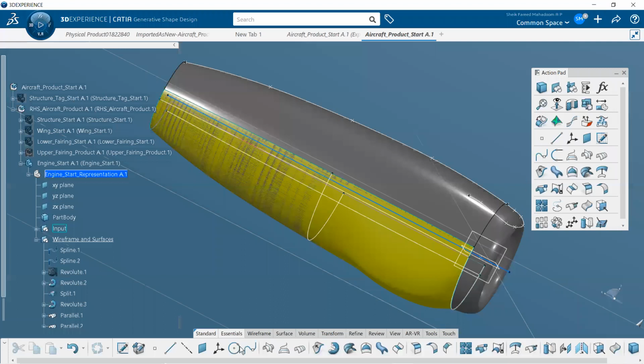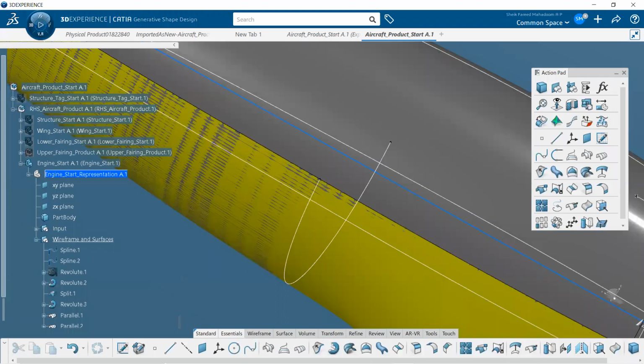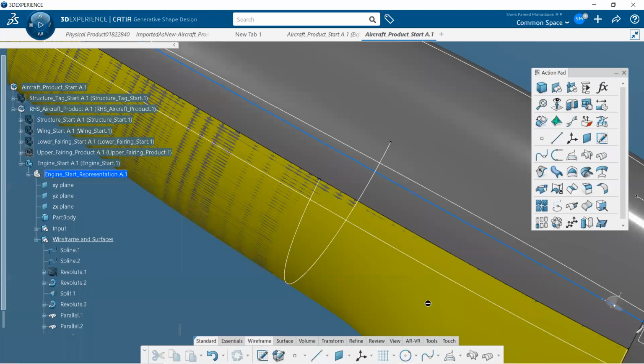Right now, to select the circle corner, just go to the wireframe, and here you will find the corner option. I will do it once again. In the wireframe, in the circle tab, near the circle, click on the arrow mark and you will have the corner option. Click on the corner option and then select this curve and select this curve.